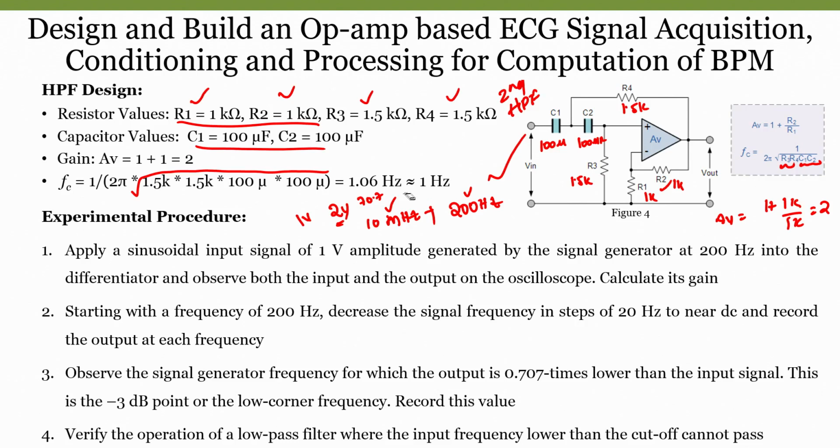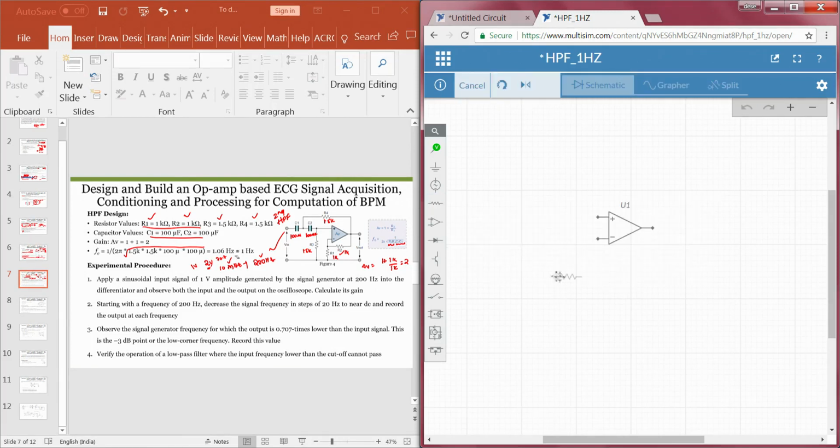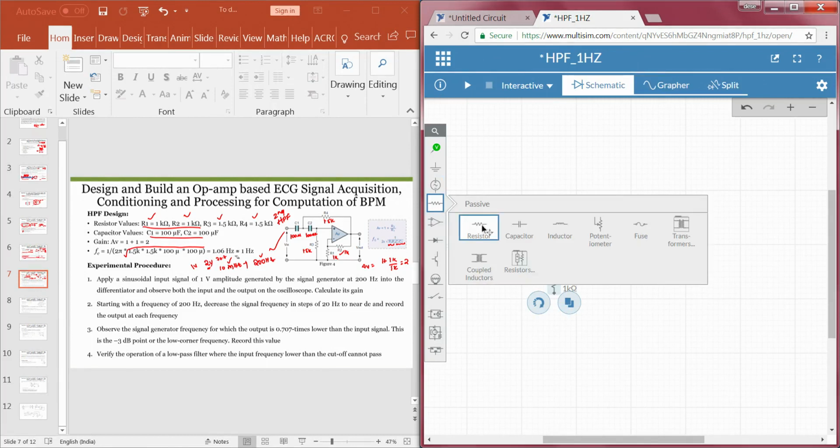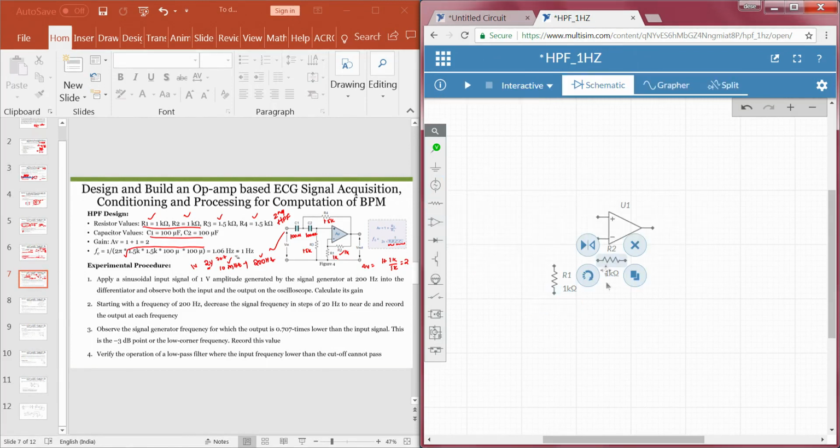So, I will use the same resistance values as well as the same R1 notations too. So, I am keeping R1 here and rotating it, and I am also taking R2. R1 and R2 are the same resistance value. So, I do not have to change the resistance, I will be connecting it here, negative feedback,